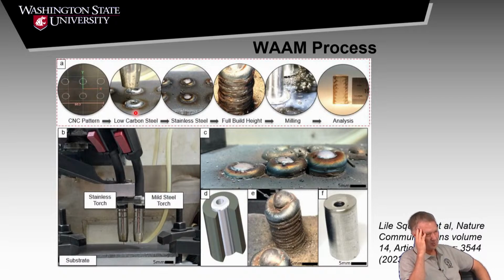Frankly, I was hoping that the texture would show us that, but the texture is showing us a component that's completely not a solidification texture. 111 fiber is not a solidification texture. So I can't determine from the texture, because of what I would say is the interference from the strain effects, what the solidification direction is. I can't do a forensic analysis like that. And we've got to do more modeling.